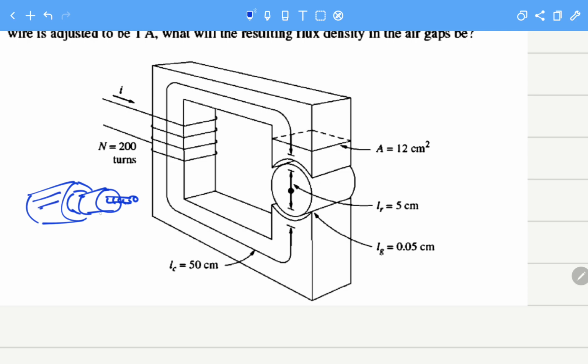The rotating part has to rotate, and if there is no air gap, this rotating part cannot rotate. So we have a stator and we have a rotor. Both are made up of ferromagnetic substances, and the magnetic flux flows through the air gap into the rotor to produce all the effects of torque and other, if voltages are getting induced, currents are flowing, everything.